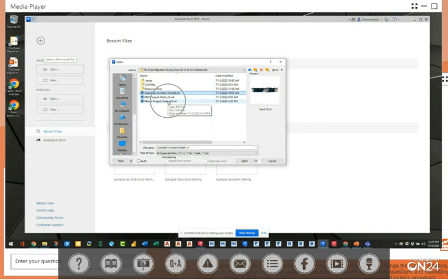So what I tell everybody is best practice is to put the version in the name of the project. So always keep this as an option. I use R as a release 23. So this tells me this is a Revit 2023 file, and I know what project and what version to open it up in. Okay, so that can help your users also, when you're working in these projects, not accidentally upgrade or get into it with the wrong version, right? So they don't have to keep asking. If you leave it like this here, you have to slow it down and wait for that, right?